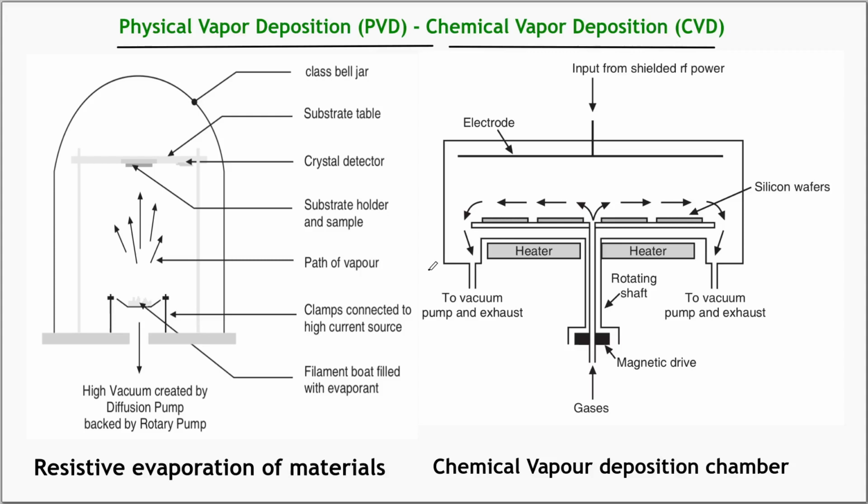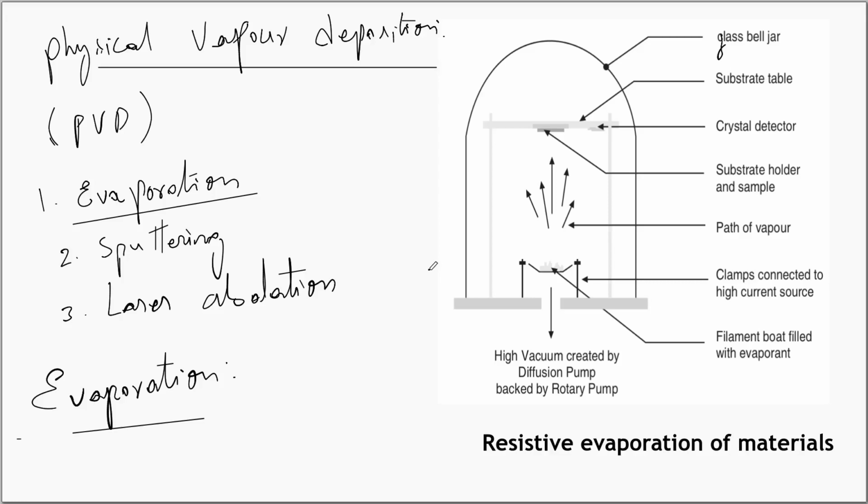In this video, we have said that vapor phase deposition essentially is used to construct multi-layered nanostructures. The vapor phase deposition techniques are broadly divided into two: physical vapor deposition and chemical vapor deposition. We started our discussion with physical vapor deposition, also called PVD for short. In PVD, the material should be transformed into a vapor. Vapor can be produced by evaporating, by means of sputtering, or by means of laser ablation. We have discussed only the evaporation method. We have discussed two different evaporation methods.